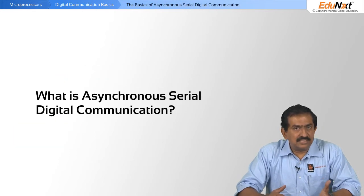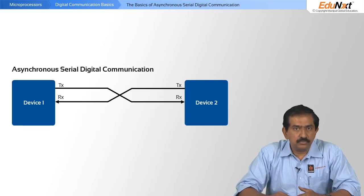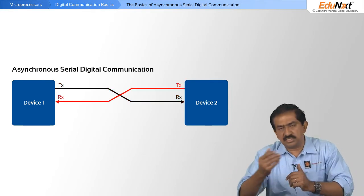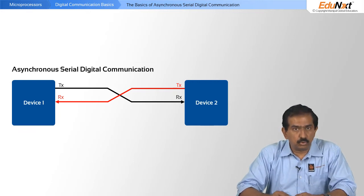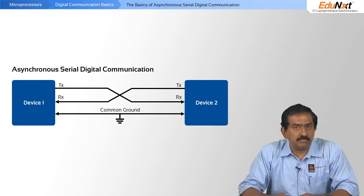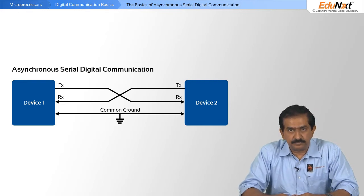What about asynchronous digital communication? In this example, you would see that the transmit of device 1 is connected to the receive of device 2. The receive of device 1 is connected to the transmit of device 2. So this is a duplex protocol. There is also a common ground signal that connects the two devices, because when the signals get transmitted back and forth without a common ground, it is normally treated as noise.